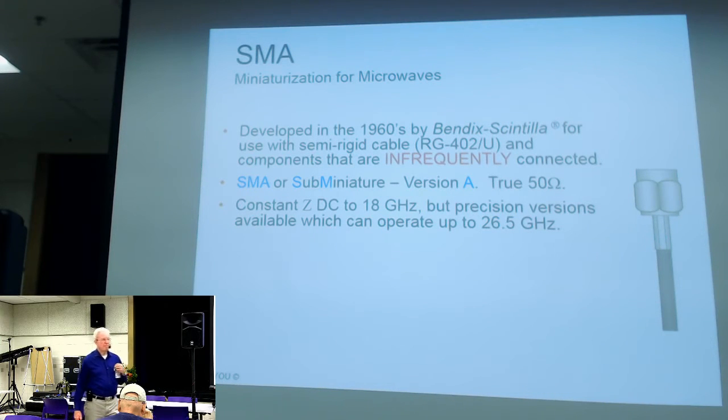Were they to fix problems in the earlier ones? No, just different sizes. Really, this is a push-on. And by the way, Ross, I soldered that. I soldered the middle pin. That is a solder crimp. You need a soldering iron with a pin tip.